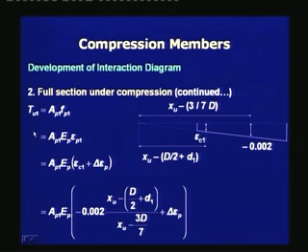Next, we are finding out Tu1, which is Ap1 times fp1, and again here Tu1 is within the elastic limit, and we can substitute the value of the strain in the concrete by this expression, which we can derive from the strain diagram. That means once we know the strain at the pivot point and we know that the strain at the neutral axis is 0, from the similarity of the triangles we can find out the value of epsilon c1 at the distance of xu minus d/2 plus d1. Thus, this expression has come from the similarity of the triangles. To the strain of the concrete, we add the strain differential to get the strain in the prestressing steel. From that, we calculate the stress, and then we calculate the force in the prestressing steel Ap1.